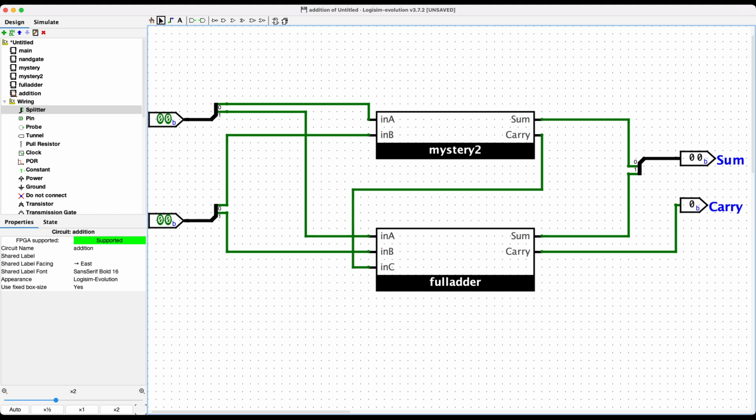Can it be instantaneous? No, nothing can be instantaneous. Is it damn near instantaneous? Yeah, okay. But see, here's the problem. Damn near instantaneous times 64 may not be very instantaneous. Okay, and so what we call this is gate delay. So the gates cannot switch instantly, right?